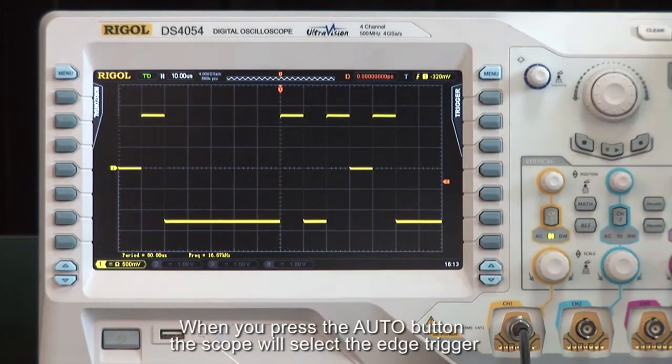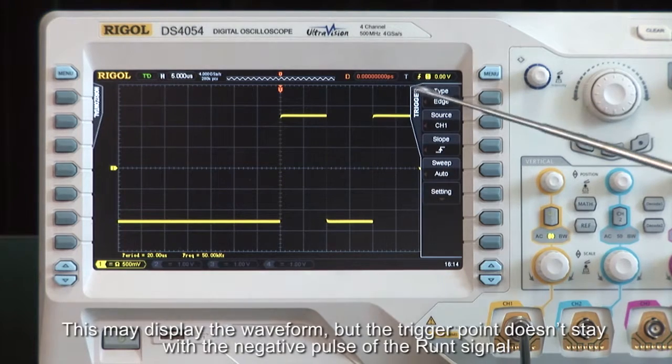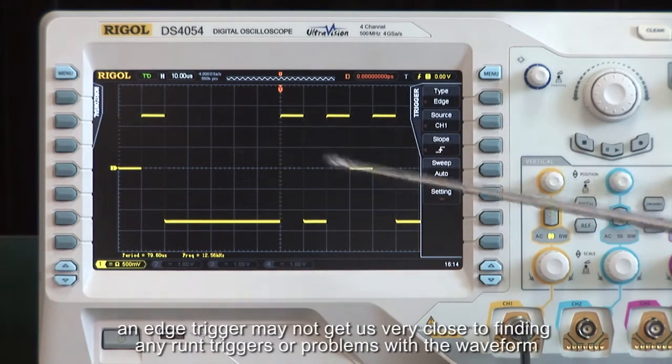When you press the auto button, the scope will select the edge trigger. This may display the waveform, but the trigger point doesn't stay with the negative pulse of the Runt signal. Since there are multiple edges on this waveform, an edge trigger may not get us very close to finding any Runt triggers or problems with the waveform.